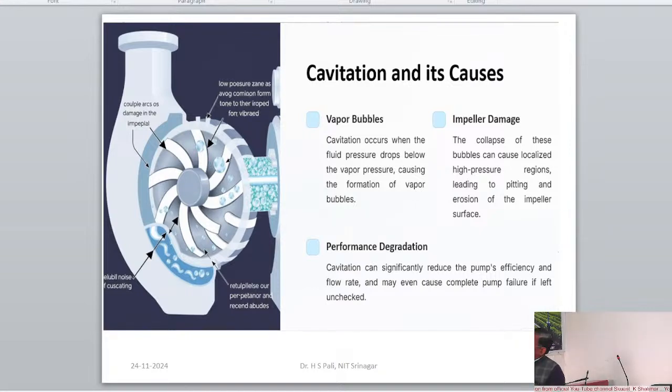These are the criteria. You can see the impeller sizes. If you want to change the impeller sizes, accordingly the flow rate will vary. If you want more flow rate or lesser head, or less flow rate and more head, then you can change the size of the impeller, because it all depends upon the input energy. So input energy is converted into the performance output energy, that is the performance rho QH.